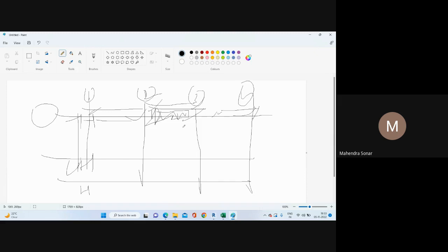Then after all those criteria, there is some plinth here, a chemical plinth, meaning some pump or chemical tank is situated here, so you need to give a plinth or any trench location. If your purpose is creating this structure for storing chemical or any fluid, and if the fluid is filled on the floor, you need to give access to drain out. So all those things you need to consider while you are doing the design.